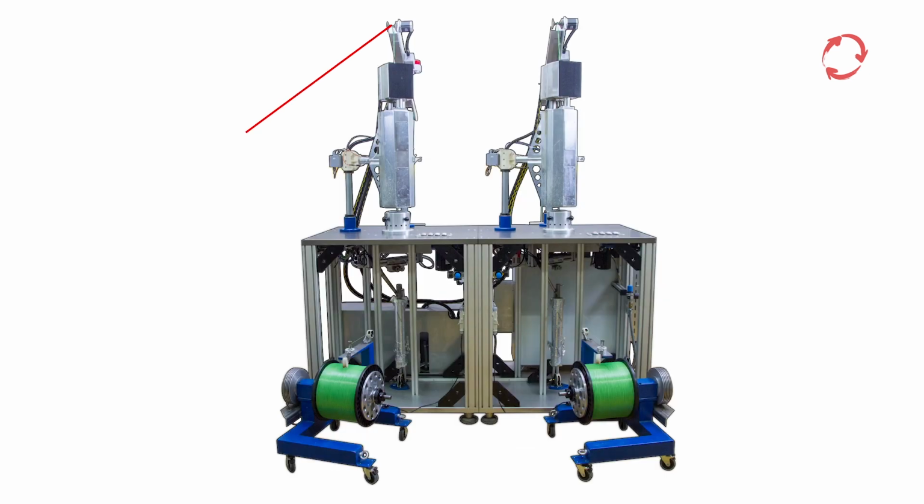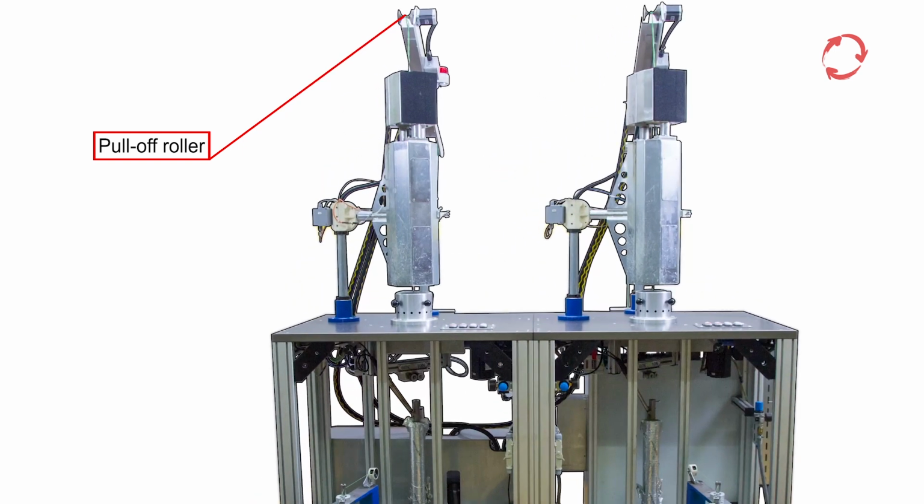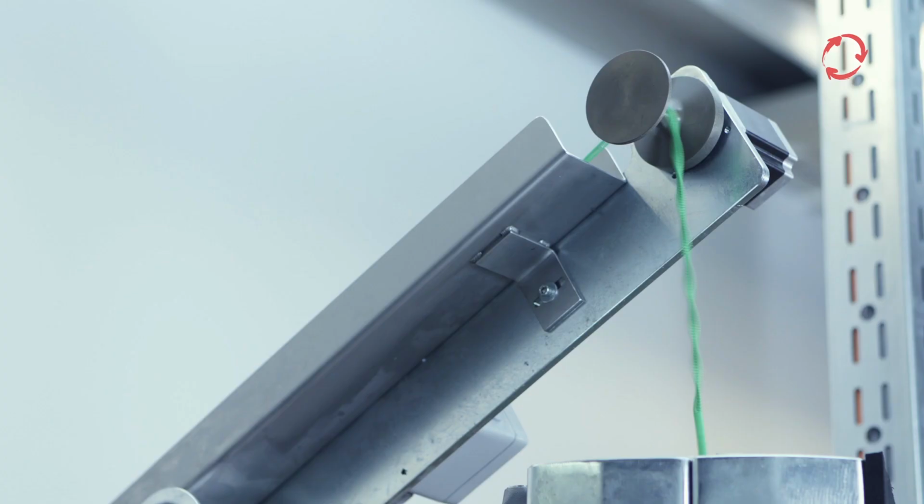The driven pull-off roller is located above the upper end of the winding mandrel. Depending on process speed and preset pull-off value, the roller pulls the spiral up from the spiral mandrel, and from there the spiral moves down into the spiral can via a downward-sloping guiding track, the slide. The spiral can also be wound 1 to 2 times around the pull-off roller in order to increase the tensile force.